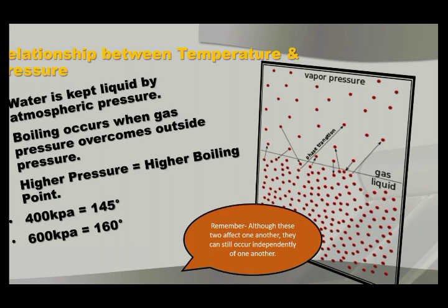Now, what does that mean? That means that theoretically, you can quite easily have 150 liters of water at 160 degrees Celsius in your roof. Now, that is beyond third degree burns. That's death. And the scary thing about it is that you won't even know that it's there unless something happens or it cools down a little bit later, whatever the case may be. But that is a phenomenon that can actually exist in any geyser if the circumstances are right and your safety mechanisms break down.